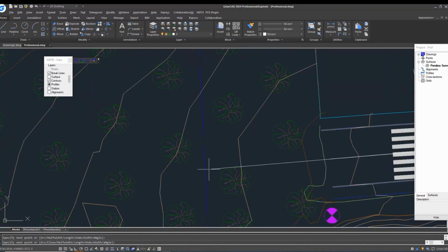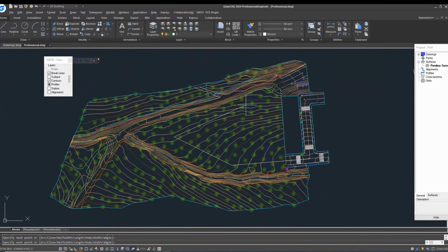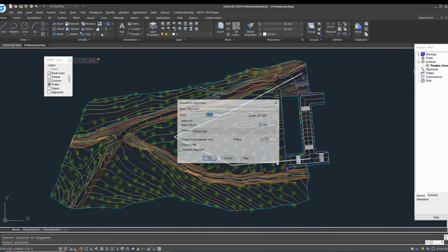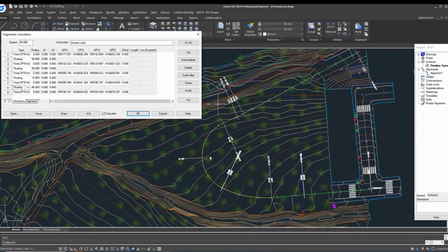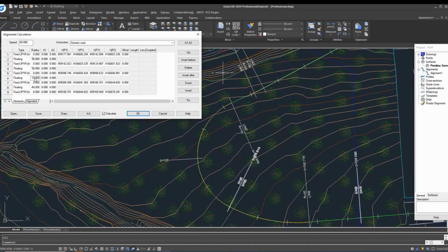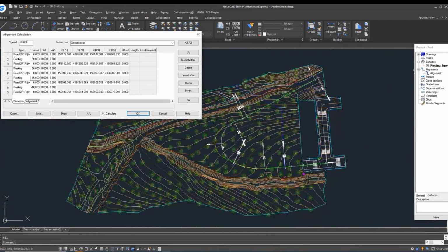First, there are two existing streets that in the example are going to be connected. Drawing a polyline, the primitive horizontal alignment, to connect both streets along the surface. This polyline is converted to a horizontal alignment, activating the option to automatically adjust a curve of radius 50 meters at the intermediate vertices. With the element tools you can edit them in real time, previewing the changes.